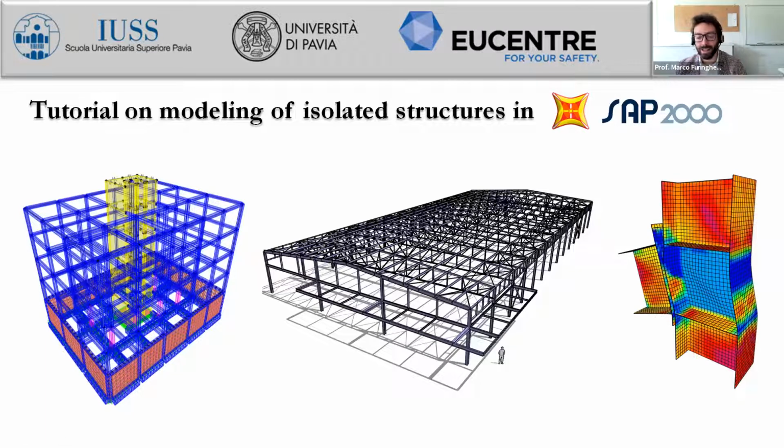I lost my vision because there were a lot of shell elements, and then the connection. I tried to model also the bolts with very short frame elements, just to provide the proper connection and the proper distribution of stresses. And finally, I found that the modal integration was the best. Actually, I could do that just because that frame structure was a reaction structure, for testing.